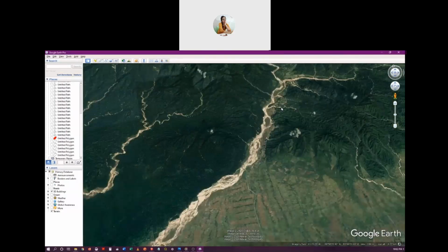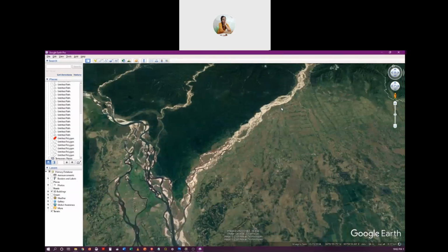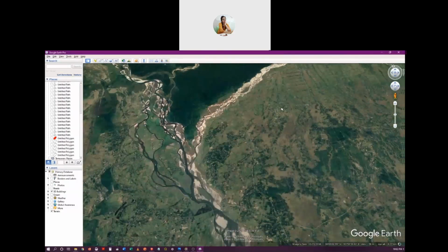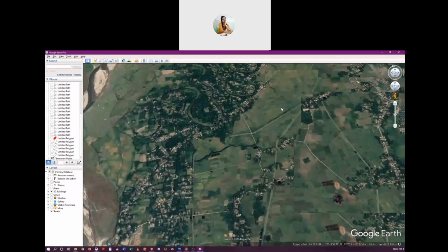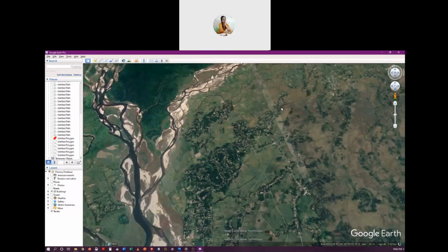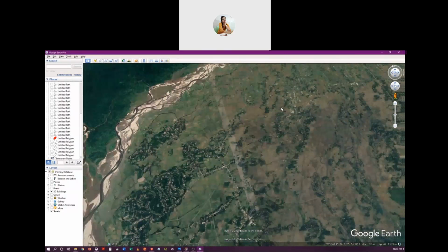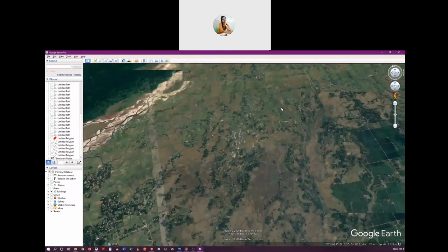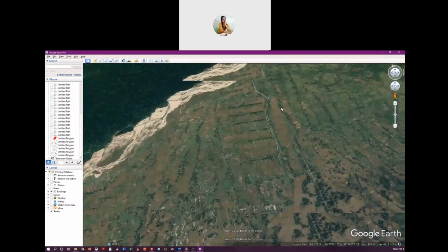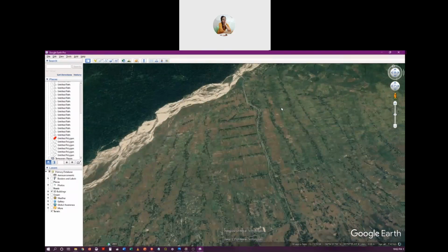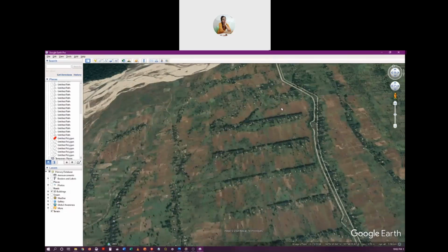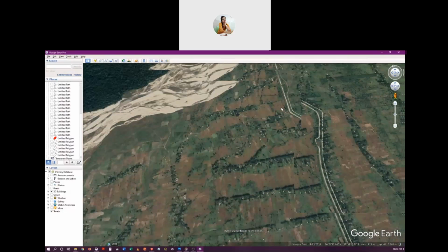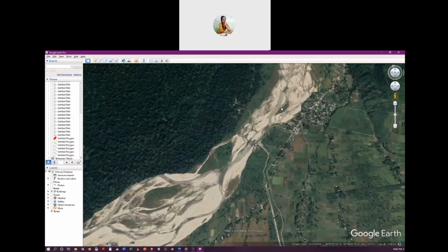And we also do not prefer a location which is much downstream, that is in the plains region, because we will then have very small amount of command area, and these upstream areas will not be able to command. So this is a kind of optimum region where we can set up our project.